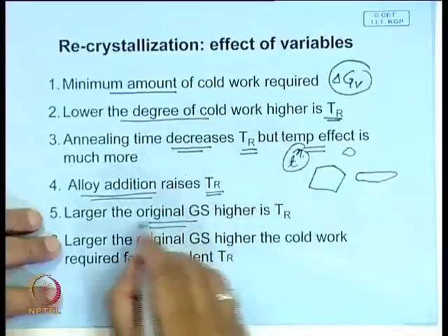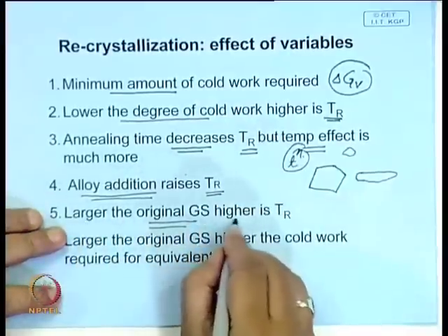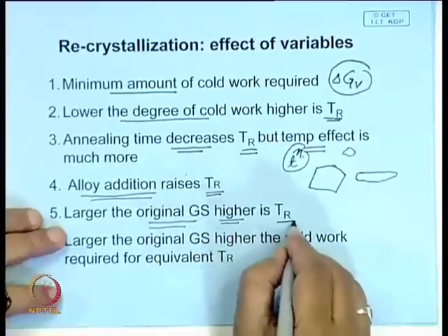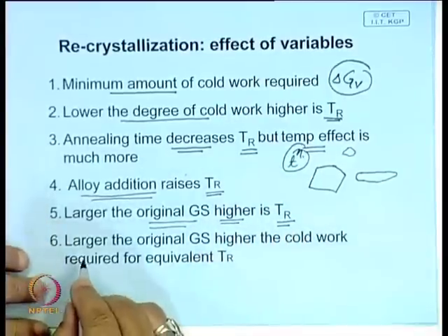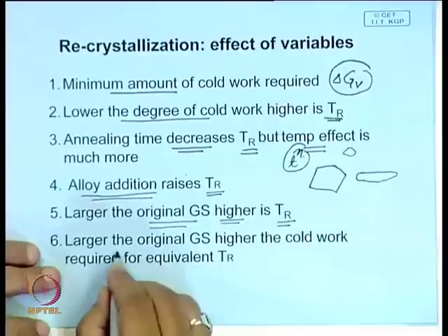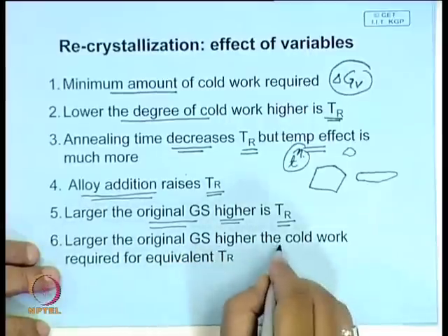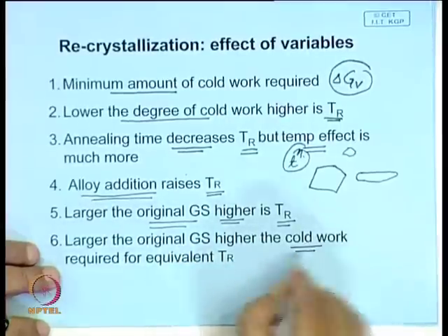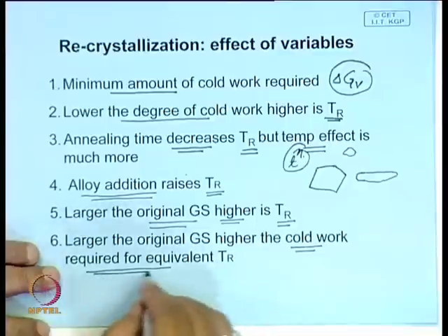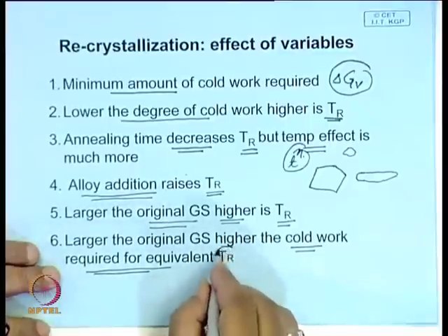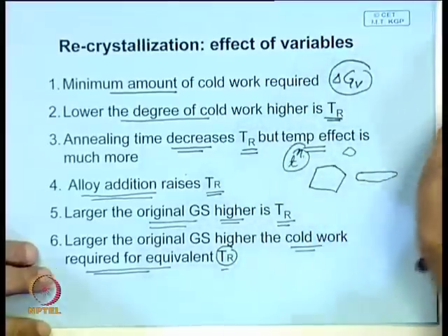So if the original grain size is larger, the recrystallization temperature is also high, and a higher cold work is required to get recrystallization at the same temperature.